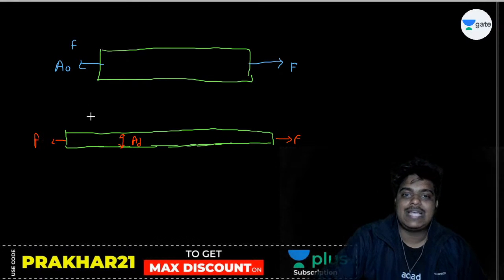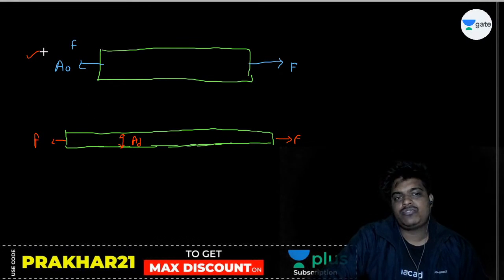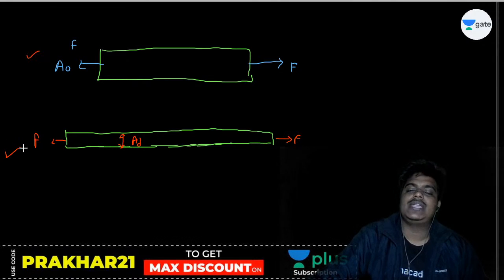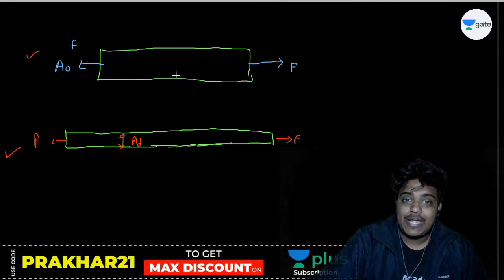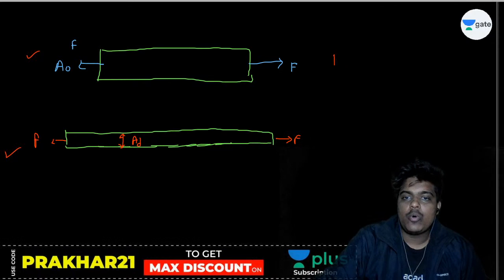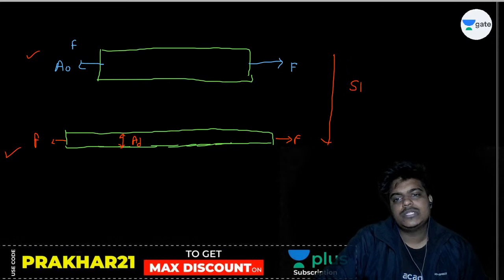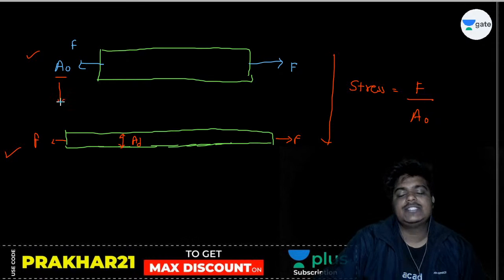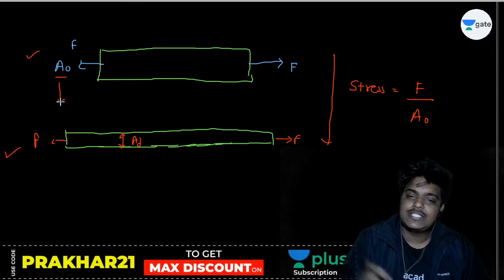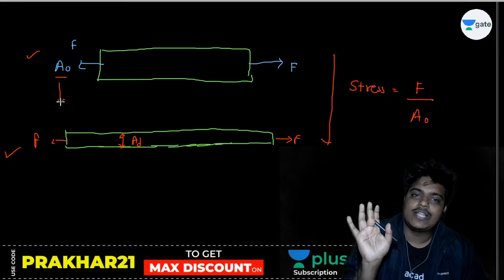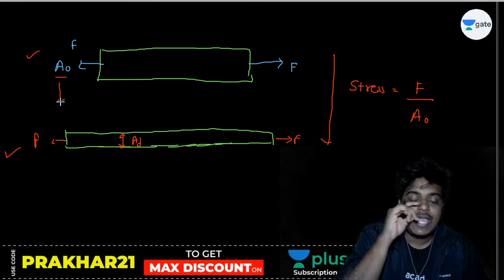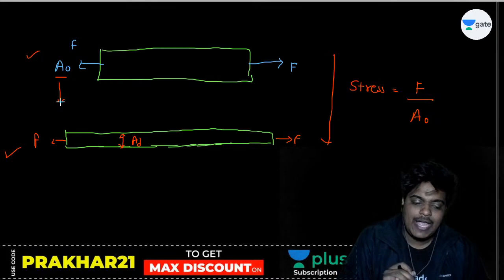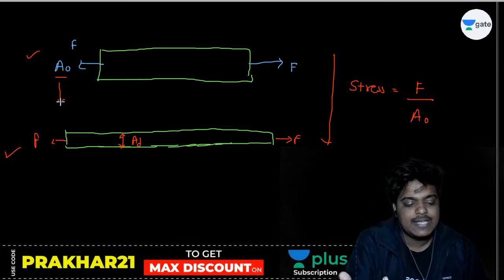Your length increased, the area decreased. But one very important thing is that you can check stress at this point or at that point, but how can I say that during the whole duration the stress was F upon A naught? No, because at every moment the area is decreasing. Yes or no? Obviously yes, sir.